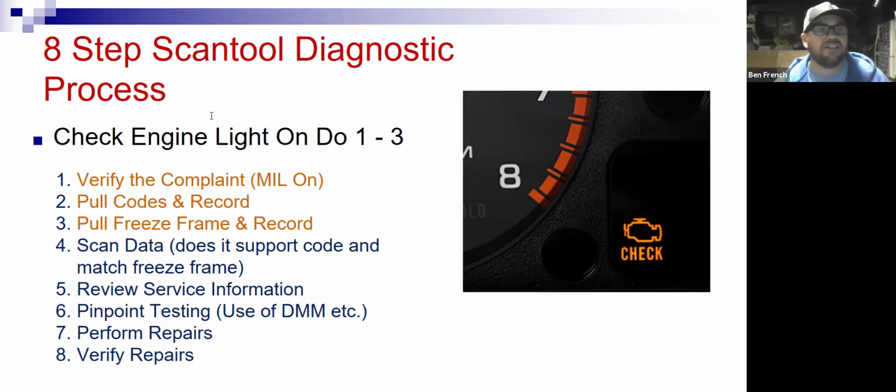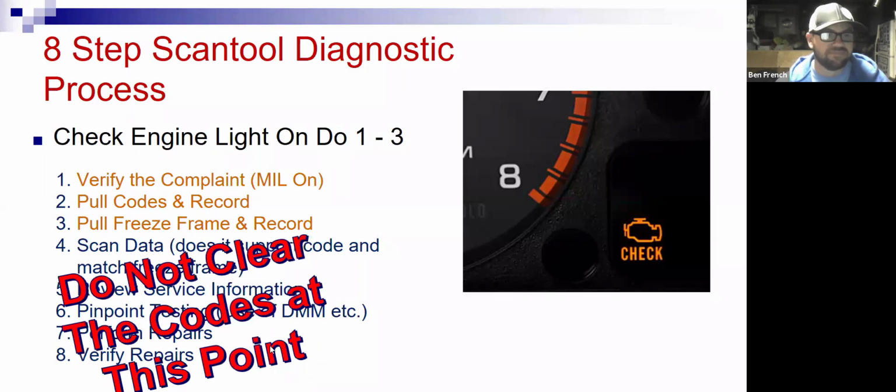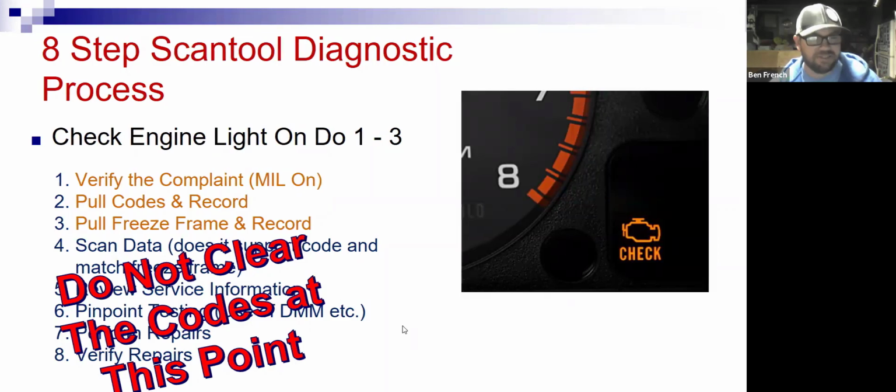So again, follow our procedure. Don't clear the codes. Pull the codes, write them down. Record the freeze frame data. Then start looking at your scan data and going on with your diagnostic. All right. Do not clear the codes. Boom.